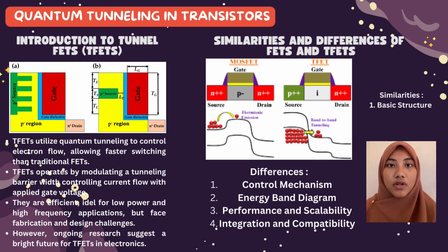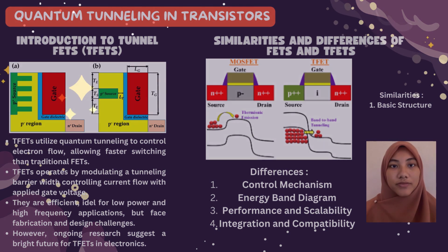In summary, while TFETs and MOSFETs share a similar basic structure, their operation and performance are fundamentally different due to the underlying mechanisms controlling current flow. TFETs offer unique advantages, such as lower leakage currents and potential for further scaling, but also face challenges related to their own current and overall efficiency compared to established MOSFET technologies.